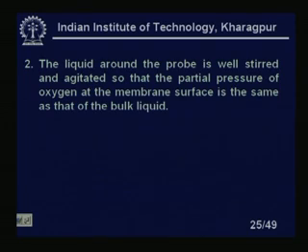The liquid around the probe is well stirred. Okay. So, mostly wherever you are measuring, it is a well stirred liquid. Whether you are using it in bioreactors or wastewater, it is well stirred and agitated, so that the partial pressure of oxygen on the membrane surface is the same as that of the bulk liquid, because we need these assumptions, otherwise it is very difficult to establish the current equations. Okay. So, the oxygen at the membrane surface is the same as that of the bulk liquid.